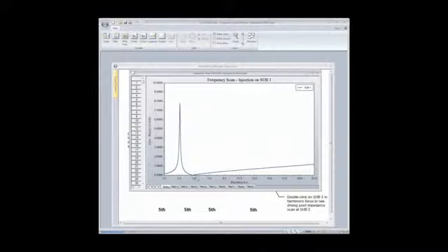We have our tuning point where it draws the system impedance down. Again, the whole idea behind a notch harmonic filter, and I might be preaching to the choir a little bit, but I'm just going to go over these things. The whole point is to draw the net impedance of the system down so that the harmonic currents choose to flow into the filter via current division rather than up through the utility transformer.